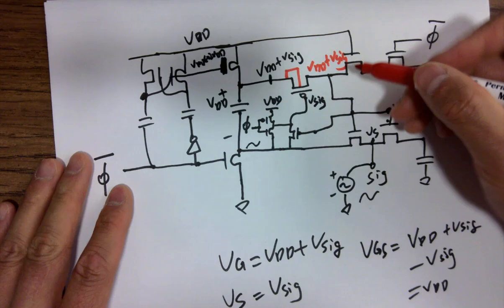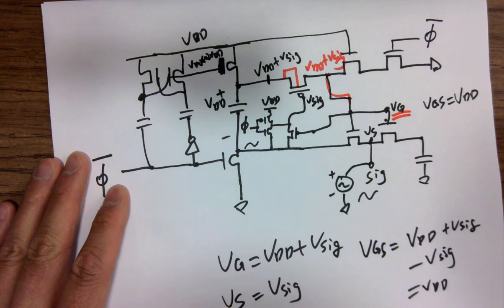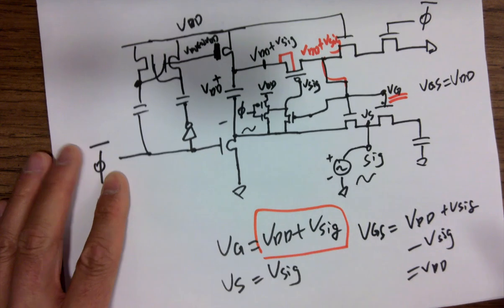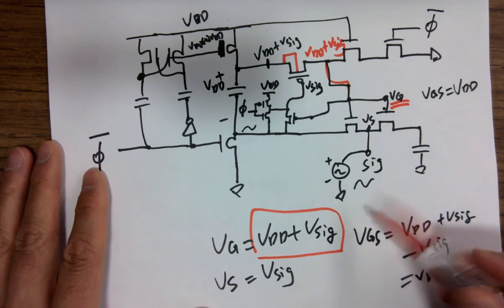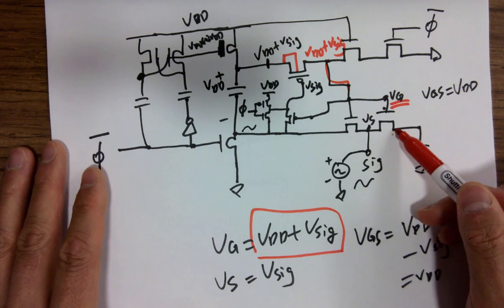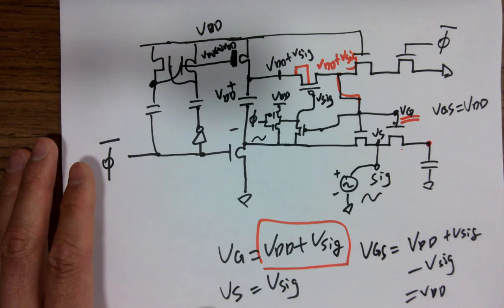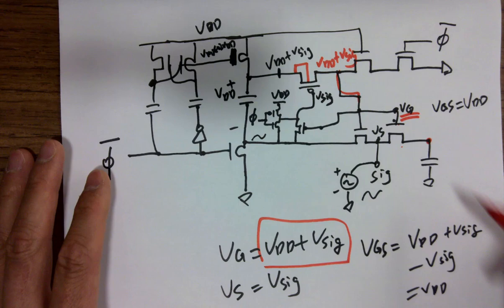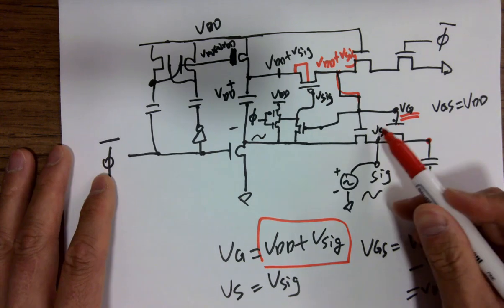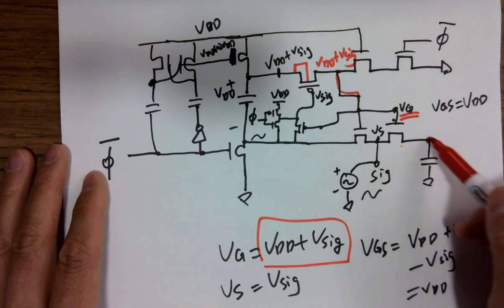All right. So this is shorted to where? Shorted to the gate of this sampling transistor. So VG is what? VDD plus Vs. All right. Are you having a constant VGS for this sampling transistor? Yes. So during this phase, what's happening at the capacitor here? There will be some internal resistance, so it's charging up with a finite amount of time because there's a little resistance over here. It's the RC delay, but anyway, this signal will charge up the cap.